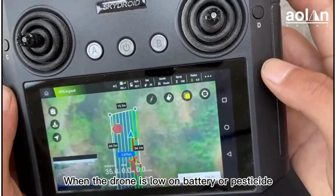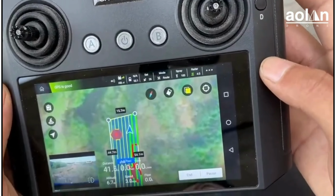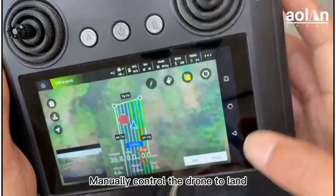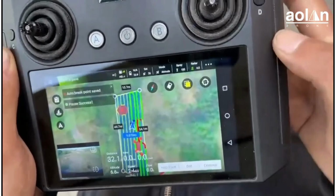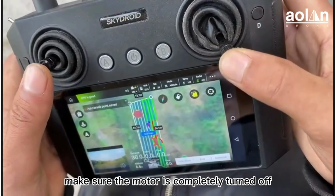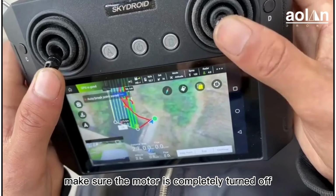When the drone is low on battery or pesticides, tap the pause button in the lower right corner. Manually control the drone to land. Before replacing the battery or refilling pesticides, make sure the motor is completely turned off.